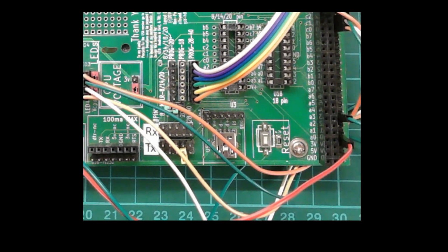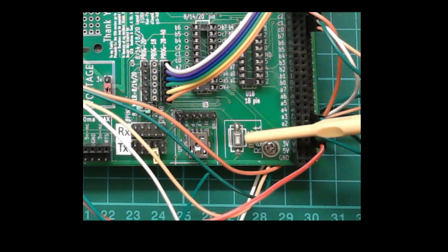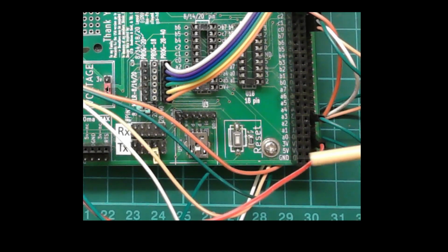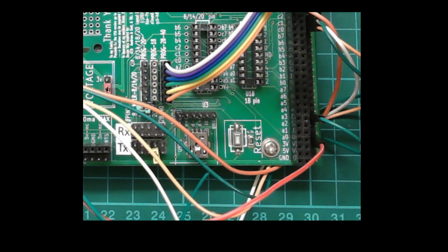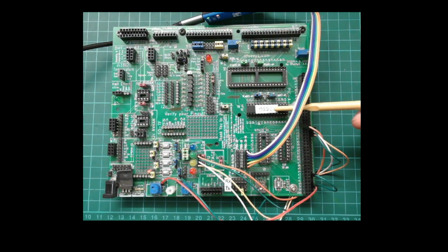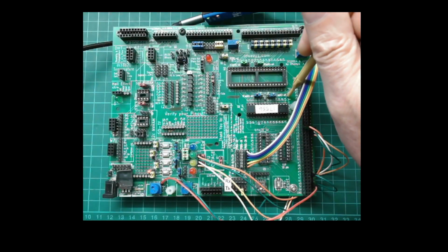Move it to the right. There we go. Look, there is my master switch. It's a reset switch. I wish I could focus in on that then. Is that a 103? That'd be a 10K pull up there. And that is connected through to the microcontroller here on RE3, sorry, which is this top right hand corner here.